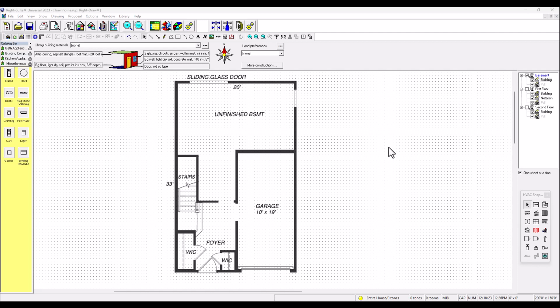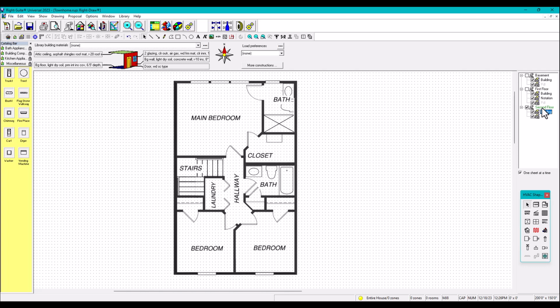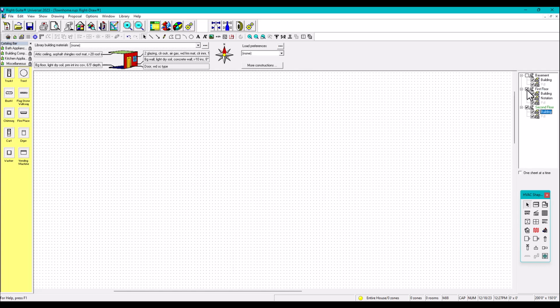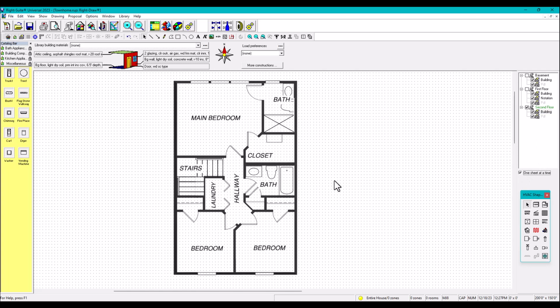Number 1. Since we already have the basement, first floor, second floor, everything is already there, like the PDF is already imported. We're going to make a quick check to see if everything's lining up. I'm going to go one sheet at a time, uncheck that, and see, I'm on the second floor, if the first floor is actually lining up. Check that. Yes, it's lining up, a little bit offset, but it's tiny. Now let's check the basement. Check. Again, it's lining up, a little bit off, but still lining up. That's a pretty good check that we need to make, because otherwise sometimes we get into trouble.